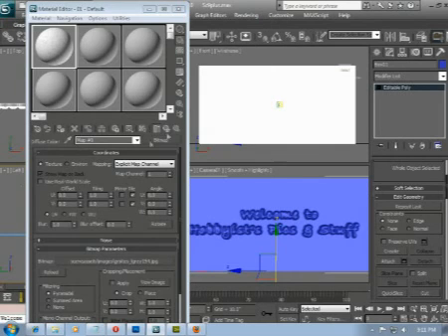Now, that puts us up on the diffuse color branch, where we set how we want to tile our 100 by 100 background swatch over the face of our box. Since we set up our camera to make the 8-inch model dimension take up exactly the width of our image, and we set the output width of our image to 800 pixels, the math is dead easy. We need to tile the swatch 8 times horizontally and 4 times vertically, and we want the little check marks checked to enable tiling. It's hard to get an idea how the skin will look on a flat surface from looking at that ball in the sample slot. Let's just set the sample object to a square.